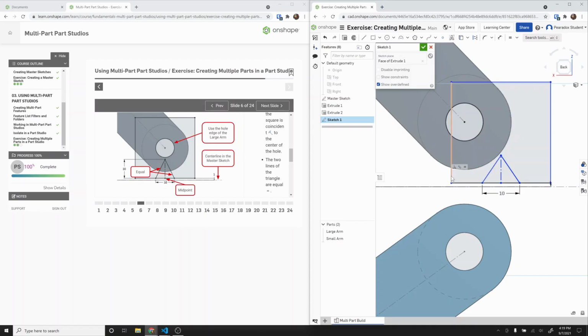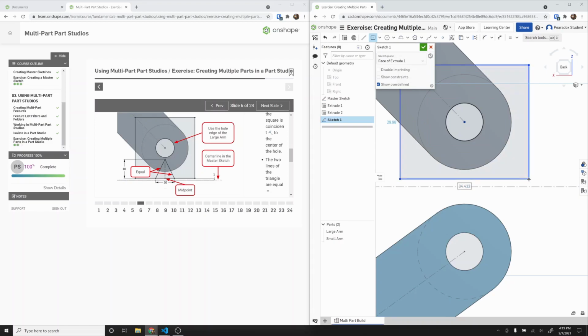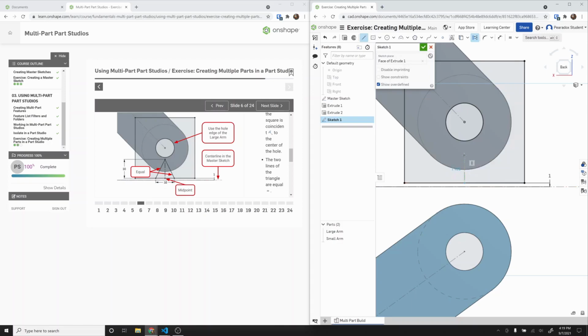You know what, I'm going to change to using a different type of square. So I'm going to delete these things. We'll just delete all this. I'm going to create the center point rectangle. And we want to go D1. And then we want to make sure that these are equal. And then we need our construction line in the center. Then our non-construction lines over here. And make this be 10.